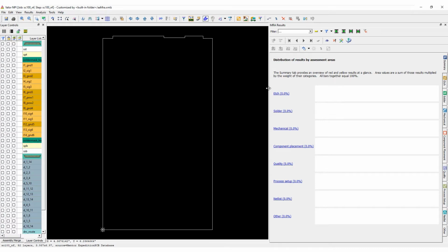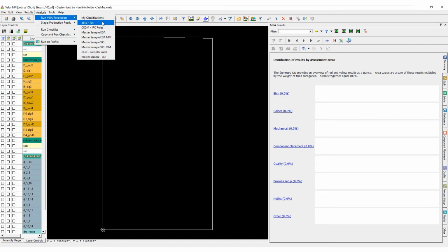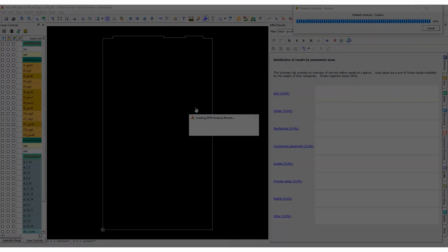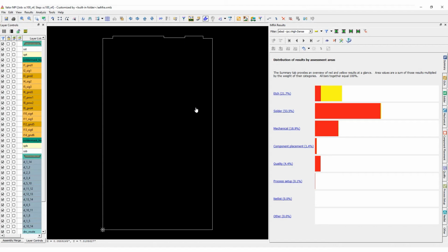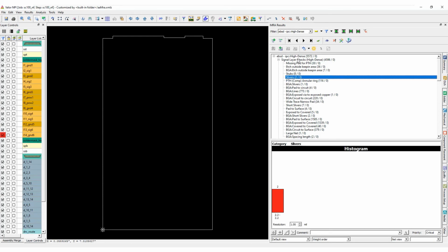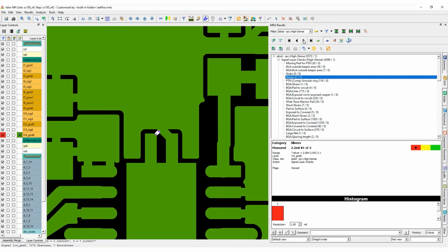Valor NPI goes beyond these typical DFM checks and also compares the design netlist against the manufacturing data. Additional to that, it even validates the manufacturing BOM matches the design by comparing all components in the approved vendor list against the design components. DFM validation further categorizes and prioritizes the design change requirements, so that you may easily resolve the most critical issues first. The weight assigned to each check is definable, enabling you to decide how the result should be prioritized.